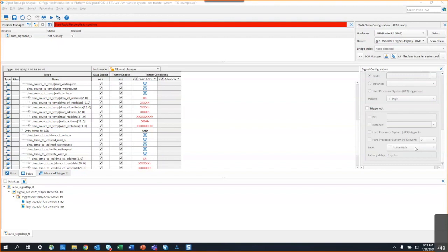I'm not sure. Well, you say the data keeps changing, but I guess you're saying that you're not expecting it to be changing. Is it like reverting back to a previous sample or something? It's not entirely clear what you mean by the data keeps changing. So is there any more detail on that, Susanna? Well, I think since it's a faster sample clock, he's probably just seeing the transitions happening. So he's sampling at 250, but really the clock domain it's coming from is 125. Yeah. Sorry, can I explain?